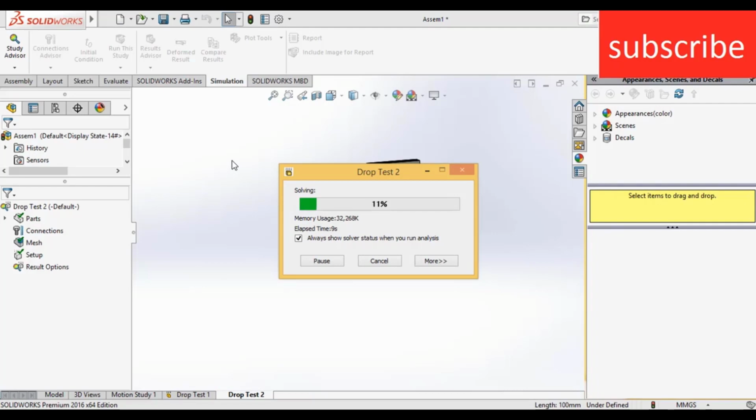After this I will tell you how damping affects the simulation when you give it some value. For example, currently what you have seen is that when a body falls or collides with the surface, it just sticks with the surface, it is not bouncing back. Why is it not bouncing back? Because we gave damping value 0. If we give a value other than 0, it will bounce. So after this simulation I will show you how to do damping.